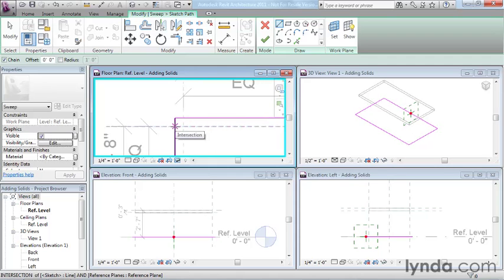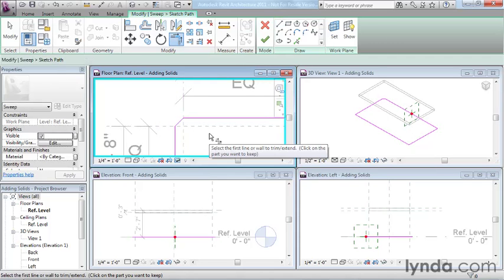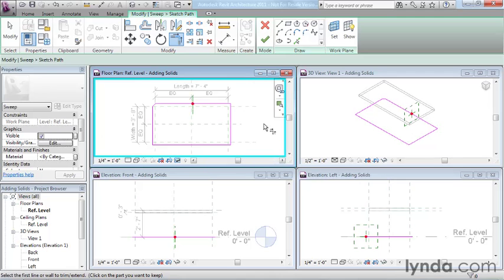Go to this intersection right here, and then that intersection there, and draw a short little 45-degree line. Click the Trim tool, and trim that corner up like so. And now I'm going to repeat that process on each of the other 4 corners. That's the shape of my 2D path. As you can see, I have a nice chamfered corner now at all 4 corners.